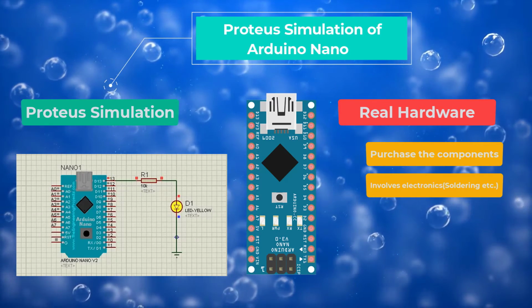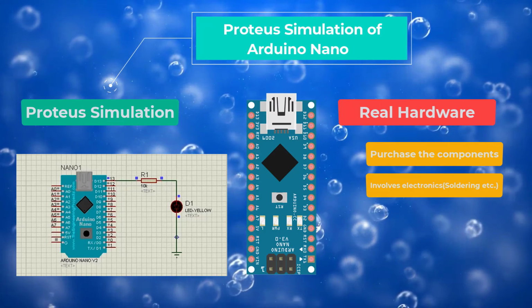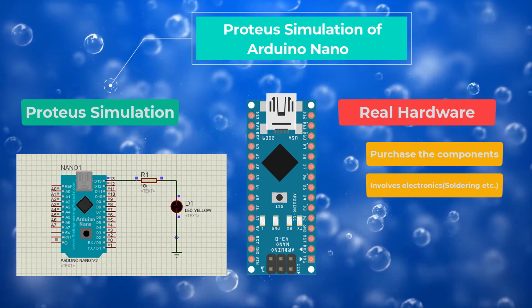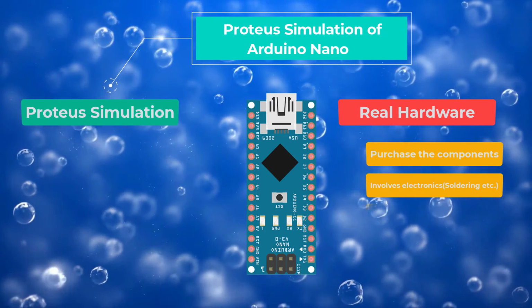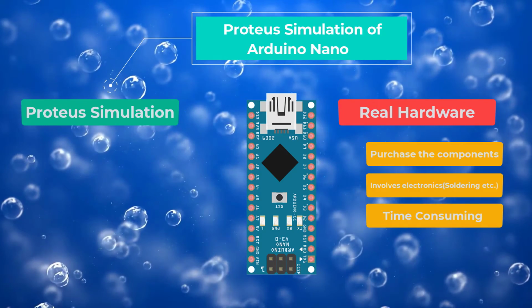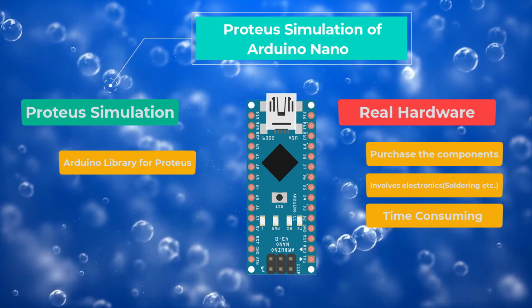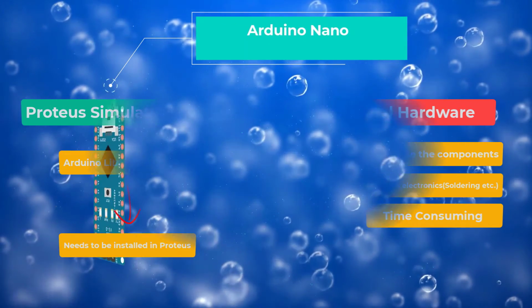In Proteus simulation, you just have to design your circuit once and then you can completely focus on your programming side. When I work on Arduino projects, I normally design my programming algorithms in Proteus, as testing with real hardware is too time-consuming. Proteus doesn't have Arduino boards in its components library, but we have designed its library, which you need to install in your Proteus software, and you will be able to simulate Arduino boards in it.